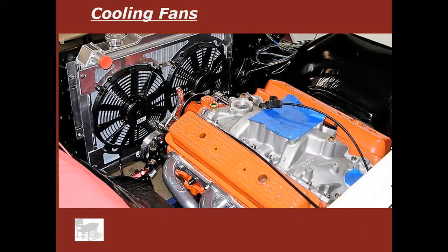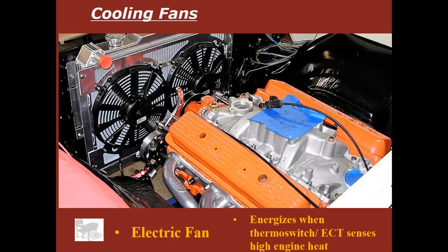So if you thought the clutched fan was the best of all worlds, how about electric fans? Okay, electric fans are pretty cool. They'll be off all the time, don't spin at all until a thermal switch or the engine coolant temp sensor senses high engine heat, and then they'll kick on. So the great thing about these is you have complete control over them via the ECU or the thermal switch. So you're not wasting any energy at all in the middle of winter.